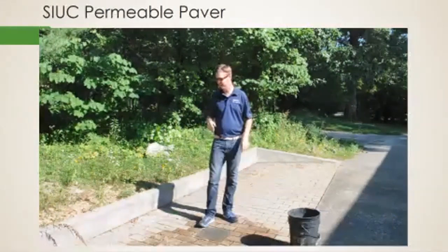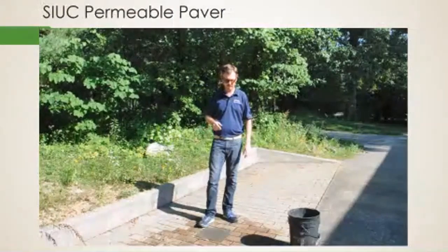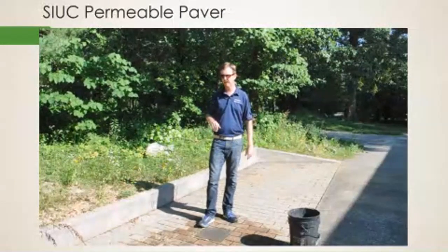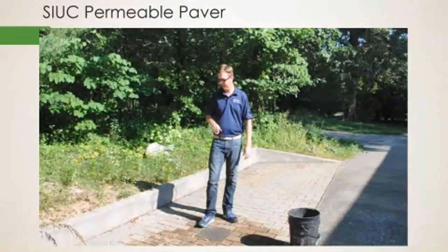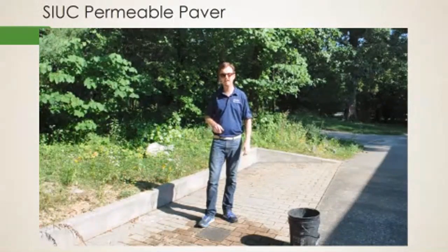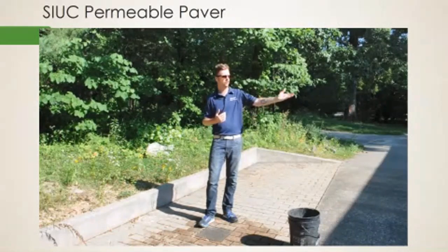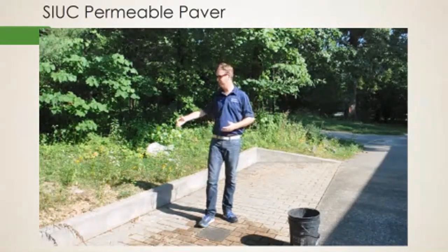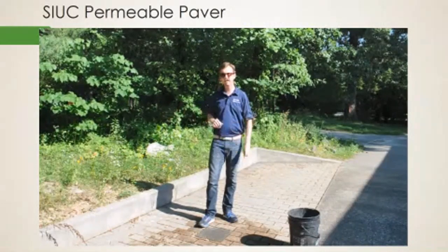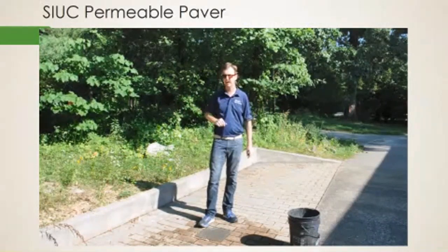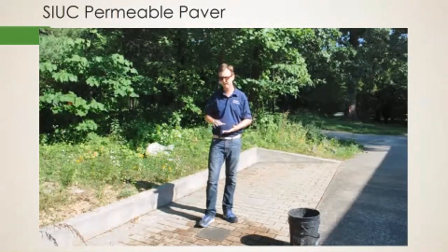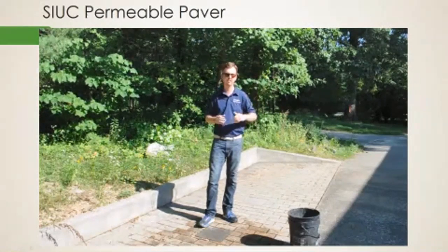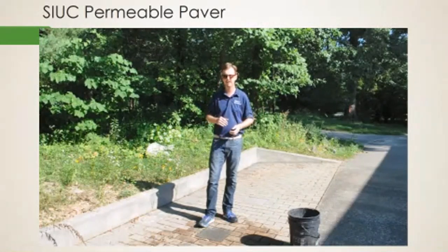And today it's nice and dry. It's not in action today, but on a day where we're getting a nice heavy douse of rain, then this is really going to do a lot to help pull in that excess stormwater off of our college building here, and to help it kind of naturally absorb back into Thompson Woods here to my right. So this is a layered system, as is the rain garden, as is the green infrastructure series that we've talked about. They're mostly layered systems.